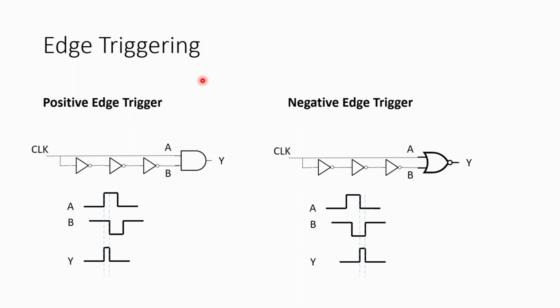Okay, so you see here we supply the clock signal like this to the input of an AND gate. In one input we supply the clock signal as it is, in another input we invert the clock signal an odd number of times. That means here it is inverted and it is also shifted a bit. Shifting happens because it passes through some gate delays. So it is inverted but it is also shifted. Now if you do an AND operation with this, you will get a high pulse between these two particular time frames, the dotted lines that you are seeing.